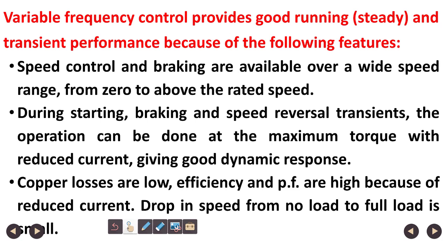Variable frequency control provides good steady state performance, good running performance and good transient performance because of the following features. First, speed control and braking are available over a wide speed range from 0 to above the rated speed. So, it is good performance. During starting, braking, speed control, speed reversal and transients, the operation can be done at the maximum torque with reduced current, giving good dynamic response.